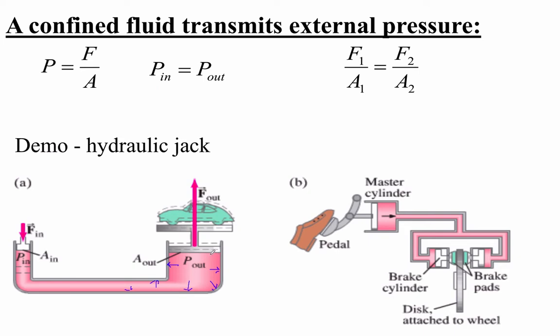Now, I know that there's some hydrostatic pressure difference, so the pressure here might be a bit less than the pressure there. We're going to ignore that, or keep our input piston and the output piston at the same level here. Okay. Now, if the pressure is the same in a body of fluid, like a hydraulic system, then, since pressure is force divided by area, if we have different areas, we can generate different forces, okay?